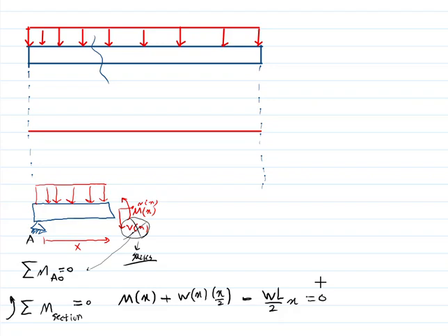So first of all, the load was uniform. The shear force was linear. So the moment is a parabola. And its amount is Mx equals wLx/2 minus wx²/2. Okay, now look at this. Can you draw it based on this without any calculations? Of course, it has a lot of information.